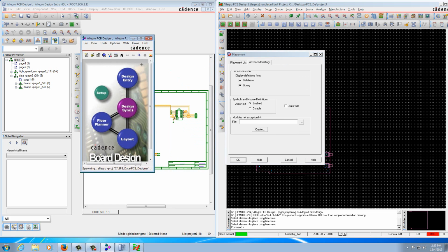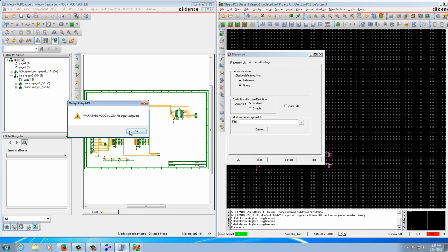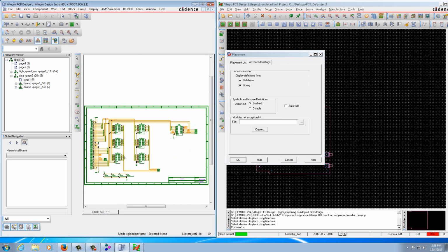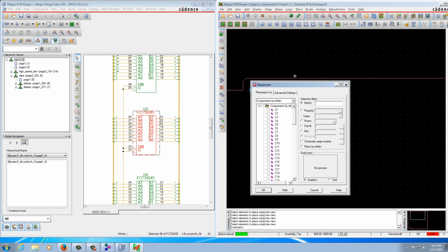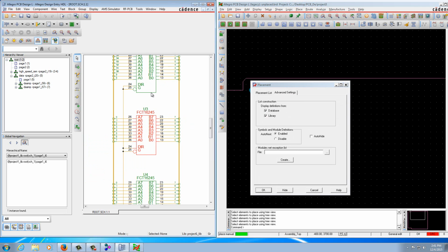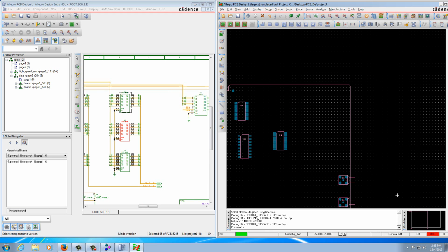It helps to select on the part outline and not one of the points. Move your cursor back to the editor window, design, to place the component. Repeat the previous 3 steps to place a few more components. After placing, click OK. By selecting the part outline, you can move the part. You can see the components are placed on the PCB editor board.